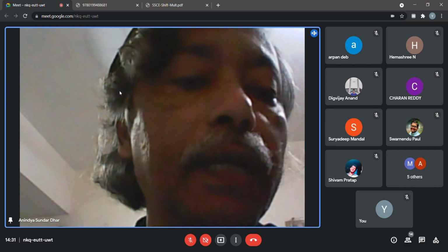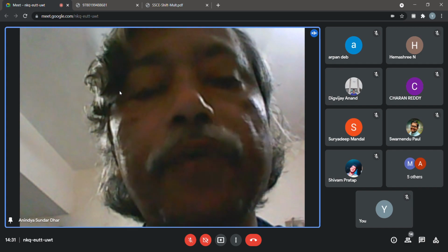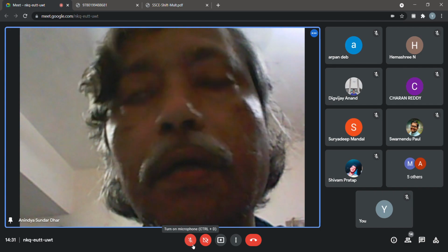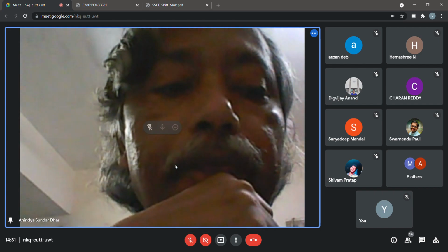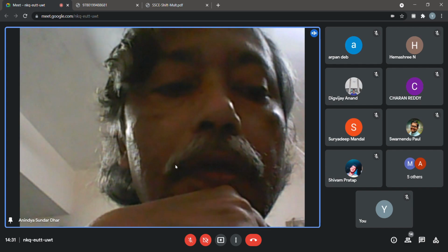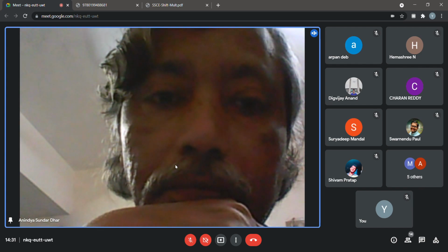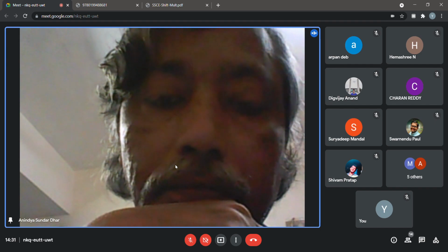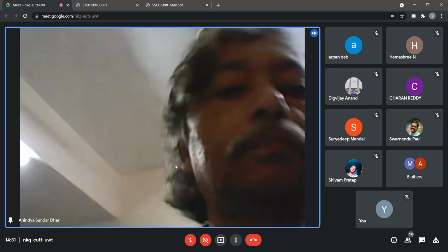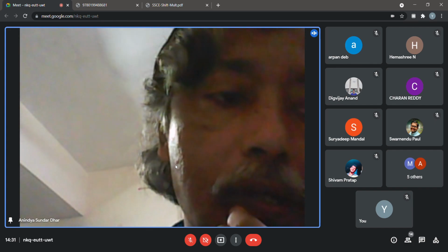So finally, what is your conclusion? I mean, a single 7483 will be sufficient, or you require 2 7483s? So we require multiple, I guess. Why do you say that? Because the inputs vary, right? We will take the first 4 bits, basically the C out, and then the first 3 bits of the output, and then we'll feed into another 7483 and we will continue. And the last bit will be stored in the 8-bit register.